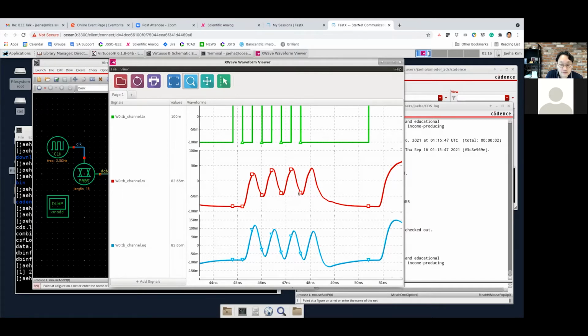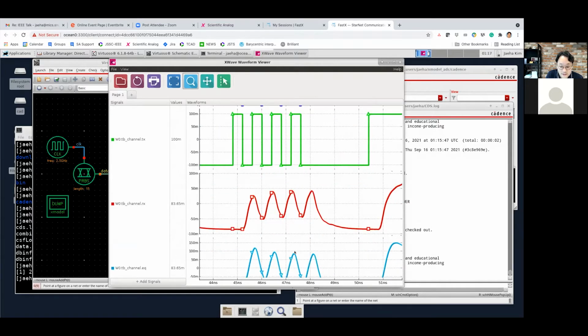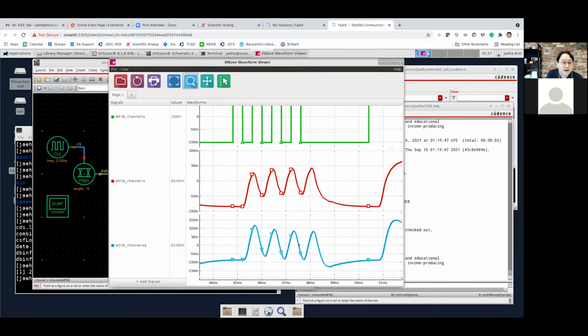In fact, some of the events describe the waveform going down and up and then down because we have these expressions describing all these behaviors. And the points where these events are being triggered are just exactly where the input events have occurred. For example, this event triggers this event, and that event triggers the event on the next stage, and so on. Okay, so this is a very simple example, but it illustrates that we can perform event-driven simulation for these analog models, all in SystemVerilog.